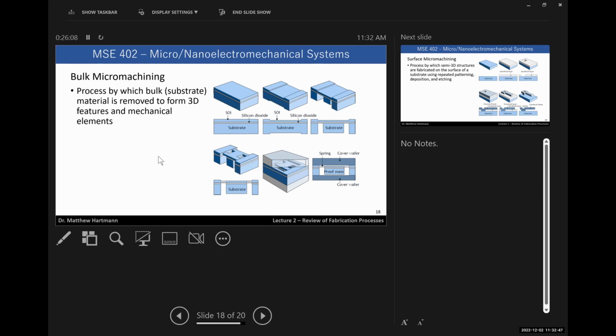And then we have a wafer bonding step where you encapsulate the top and the bottom, so that hopefully this is done in either a vacuum or at least some sort of fixed pressure, so that you know how much air damping is going to happen, so that you can translate that into a measurable electrical signal or known quantity. Okay. So this is the bulk micro machining process in a very simplified view.